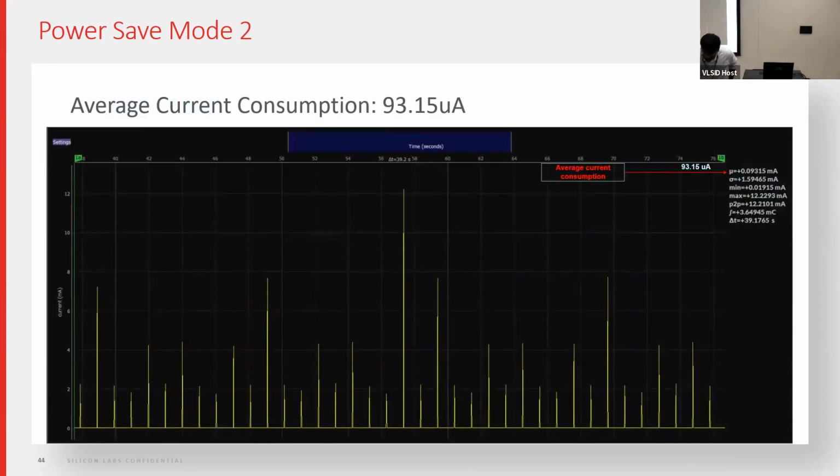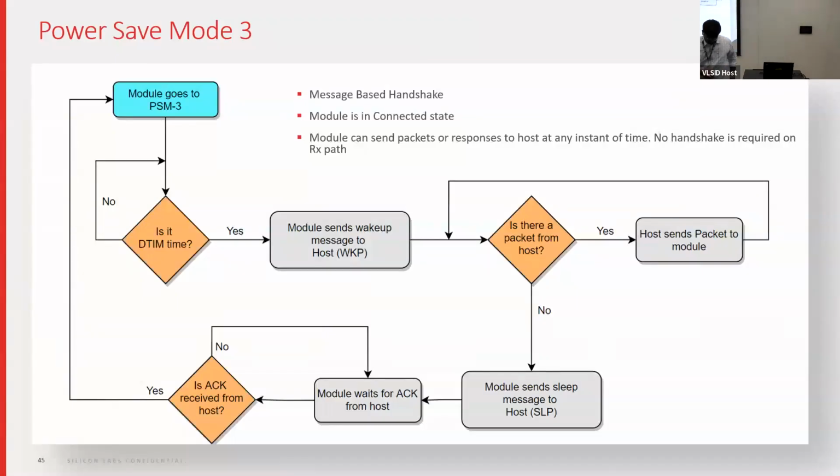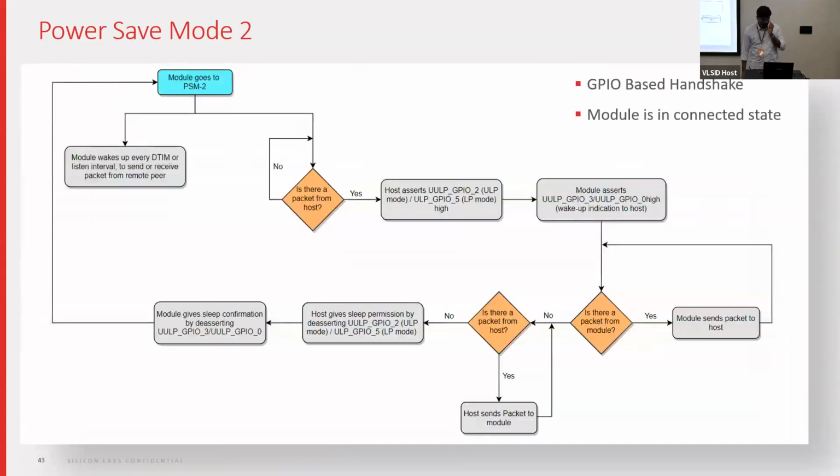Receiving cannot be asynchronous, because if somebody else wants to send you data, it comes to the access point. The access point sees that the wireless device appears to be in sleep state as announced by it, and then it just queues the packet and marks it. Then the device, whenever it wakes up, has to retrieve the data. But a transmission can happen anytime. It's your choice. If you feel your sensor data is not important, you may be sampling your sensor every, say, half a second, but you may choose to send it once in 10 seconds, the last 20 collected samples. It's up to you.